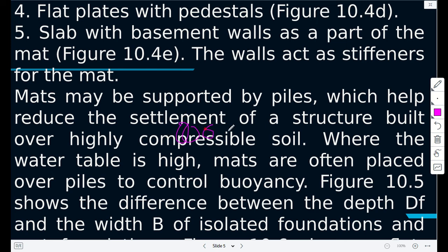The same idea. So you put rocks. This rock will be, in relation to the ground for example, very stiff. So the rocks will help distribute the load in the same manner. This is what we're saying. We are saying again the idea 2 to 1, so that the overall area under which the load is transferred is much larger, and we reduce the stresses on the ground.